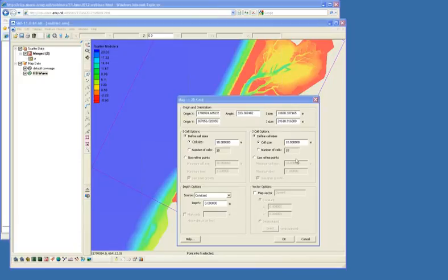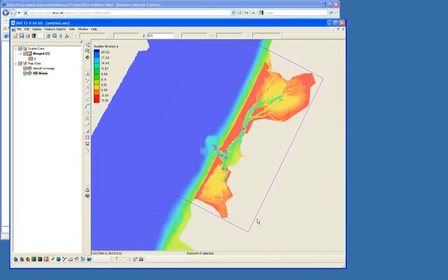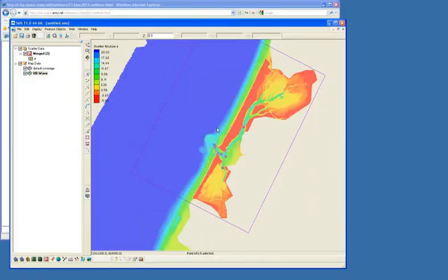Basically, the CMS wave is a half-plane wave model right now, and so that means that the waves can come anywhere from about 85 degrees normal to shore and negative 85 degrees, so any range in this direction. They would still propagate from the offshore edge, but the waves could be coming at a very oblique angle.